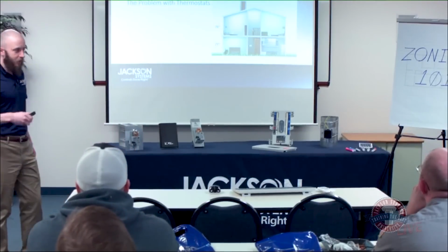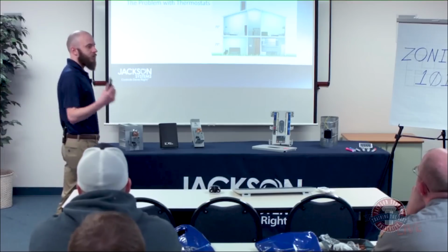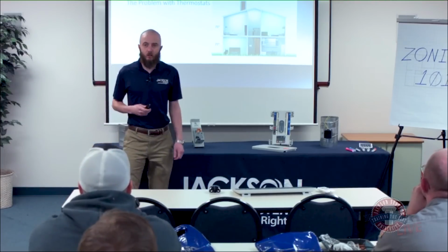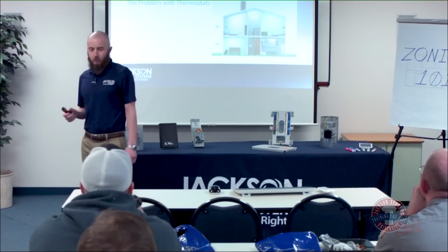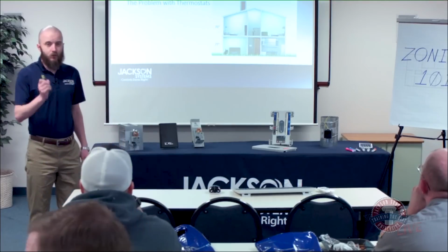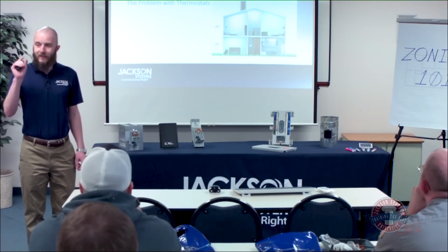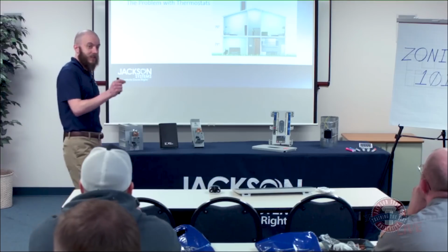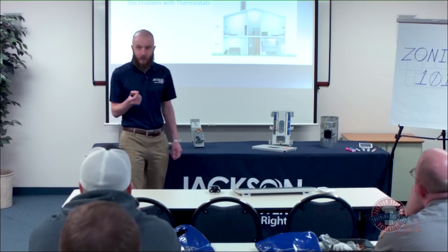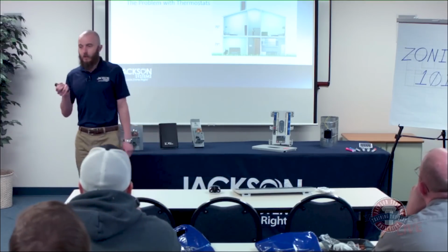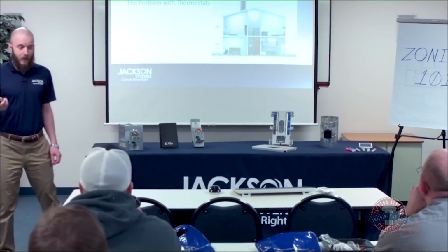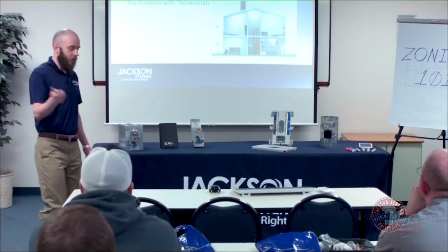If you've done your load calculations and your duct design, your equipment sizing correctly, you should be pretty comfortable in most of the house. But again, because you're controlling from that one single point where the thermostat is or wherever the thermostat's sensing from, that's the only location where you can be sure you're going to be comfortable in the house. And with HVAC, it's all about comfort.